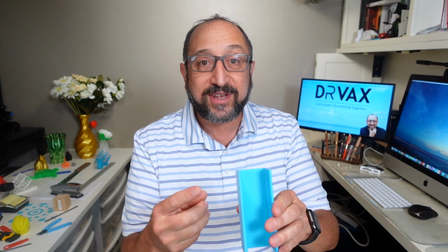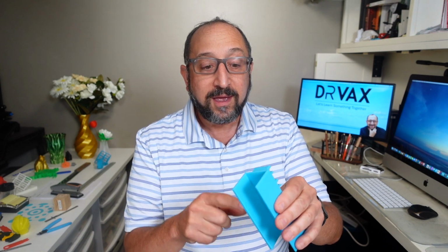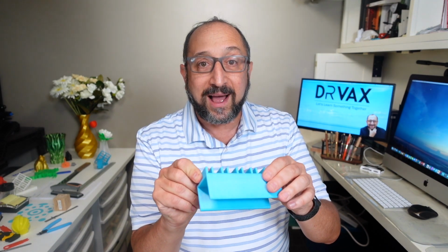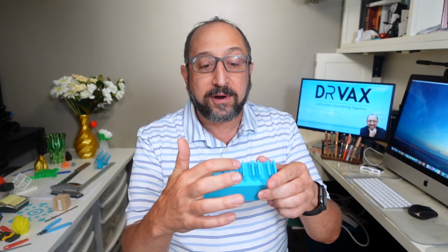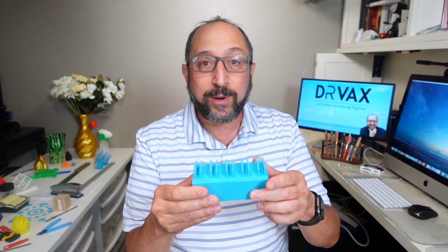So we're going to create this with 3 sketches. We're going to make a sketch for this shape and extrude it. We're going to make a sketch for the block and extrude it. And then we're going to make a sketch to cut out the middle of each block and create a pocket. So let's turn to FreeCAD and get started.